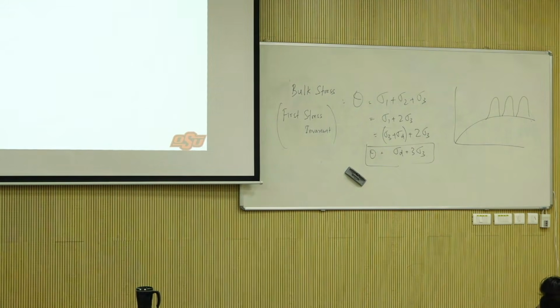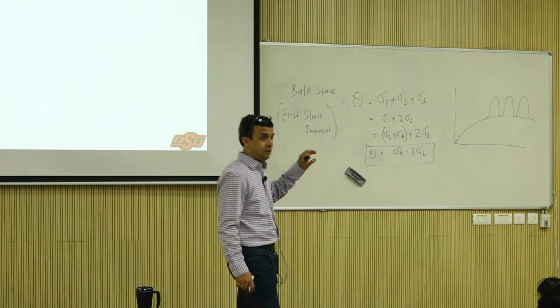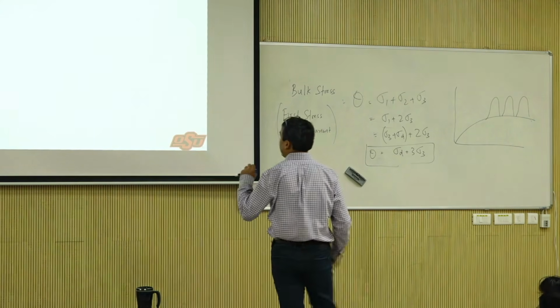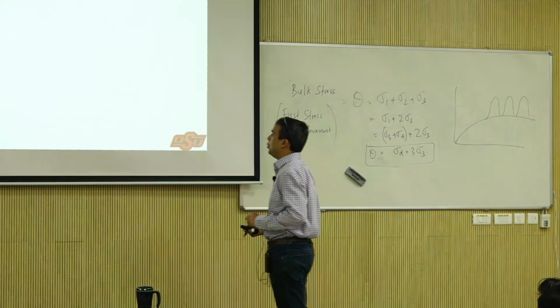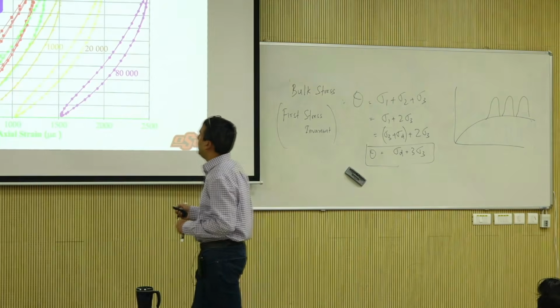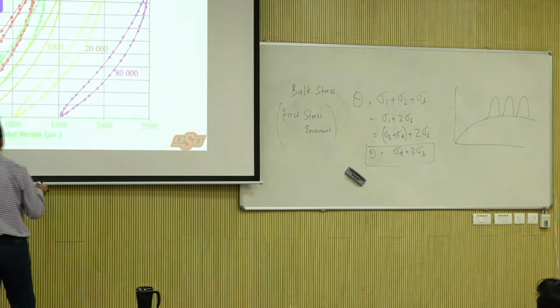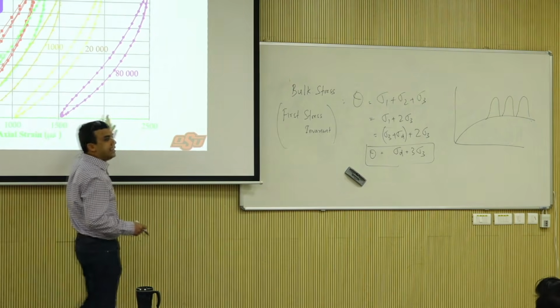Materials, we're going to talk about cohesive soils and cohesionless or granular materials. They are different. They behave differently under repeated load. And we're going to talk about testing approach. This is a typical data that you would obtain, deviator stress versus axial strain, for a granular material.